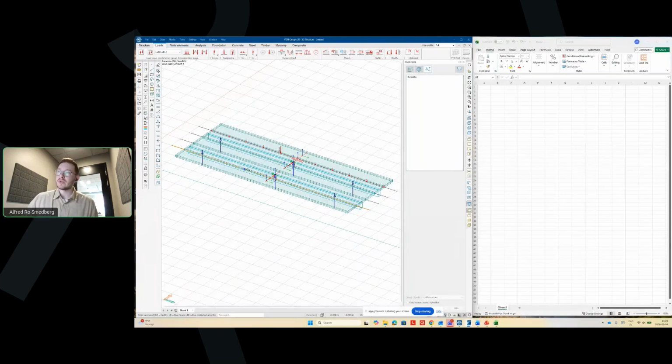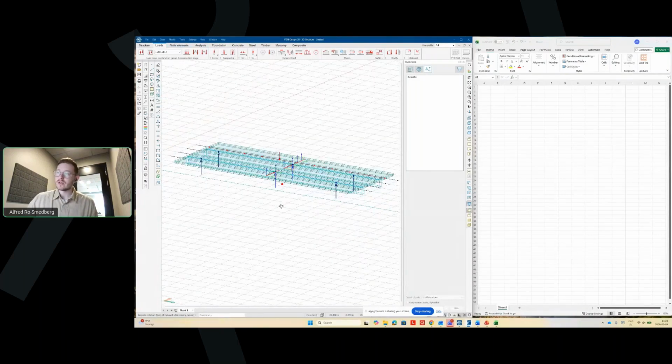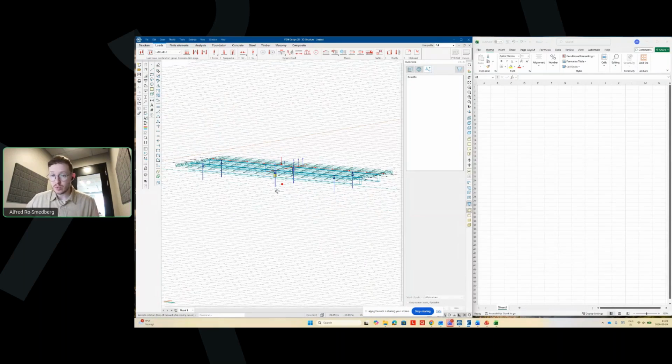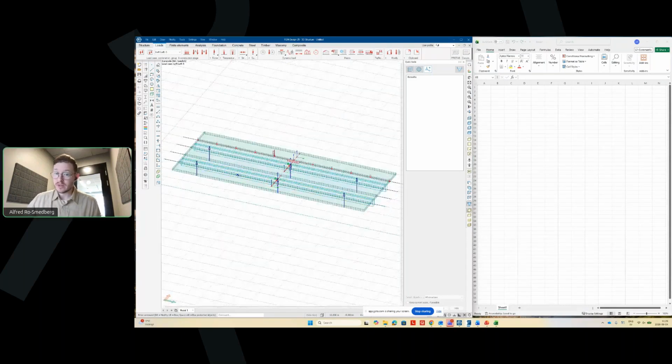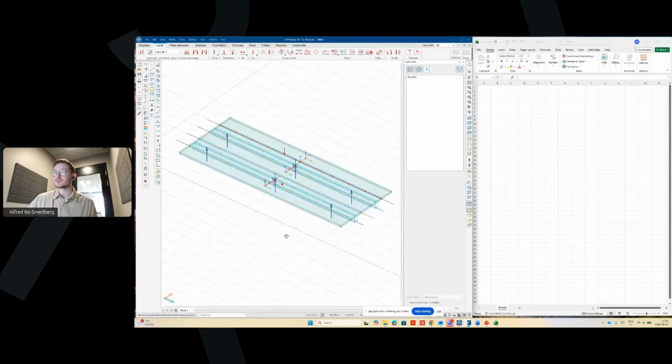But my goal here will be to run the analysis one more time with just one load case. I will look at bar results, MY, and I will look at the maximum moment results that will appear somewhere here, and then I will compare that for different types of graphs.